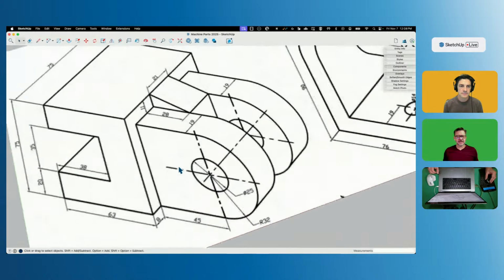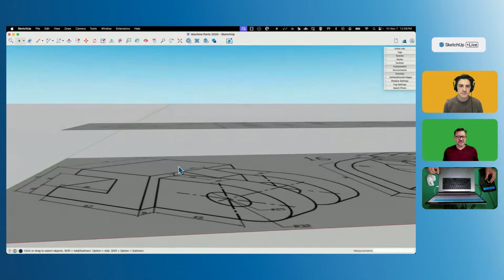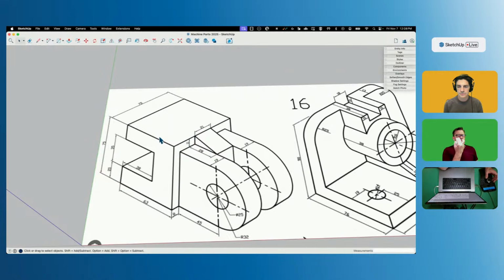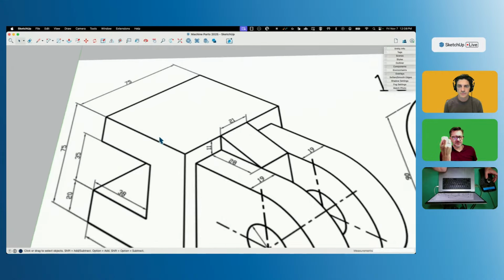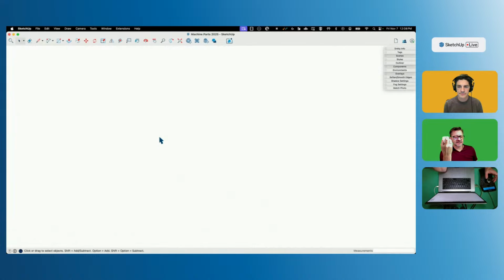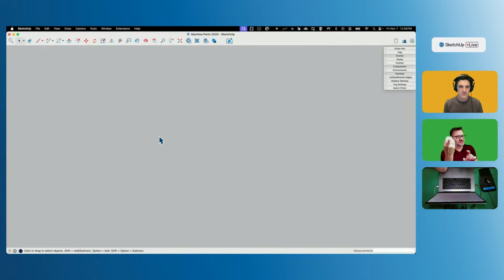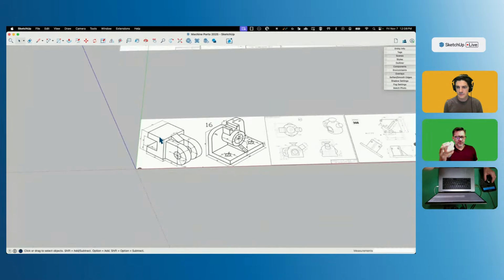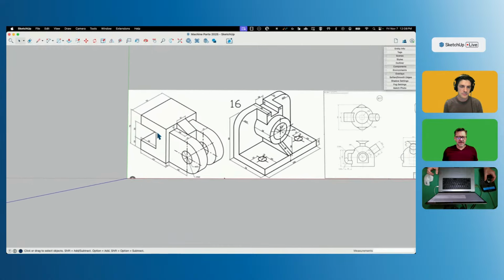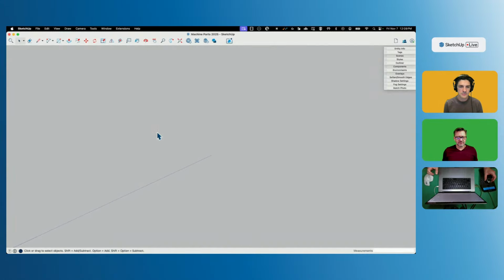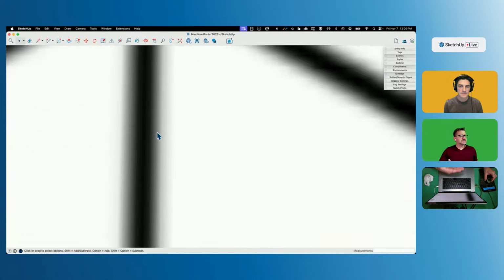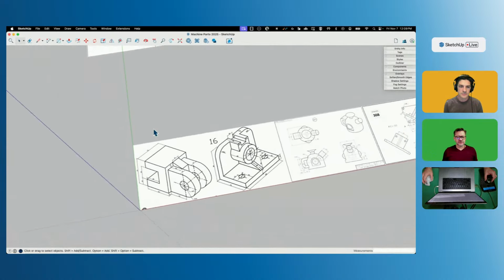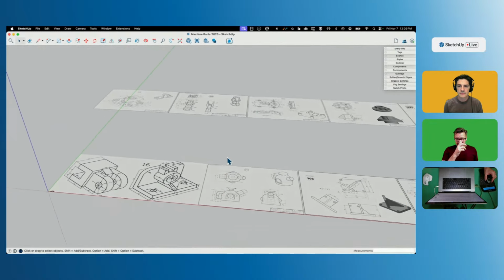The other thing is that it's a steady zoom. So when I use the scroll wheel on my mouse here, as I scroll in, the closer I get, the less it zooms per scroll. You can see I'm still zooming now, and I'm just getting closer and closer and closer to that white until eventually I break through. If I come all the way out with the 3D mouse, it's just a continuous zoom, pop right through. So it doesn't scale to how close your camera is. It's just consistent. So yeah, it's real easy.